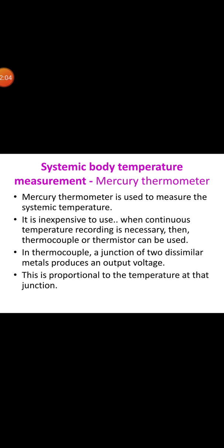The thermocouple is a sensor used to measure temperature. Thermocouples consist of two wire legs made of different metals. The wire legs are welded together at one end, creating a junction, and this junction is where the temperature is measured. When the junction experiences a change in temperature, a voltage is created. The voltage can then be interpreted using thermocouple tables to calculate the temperature.